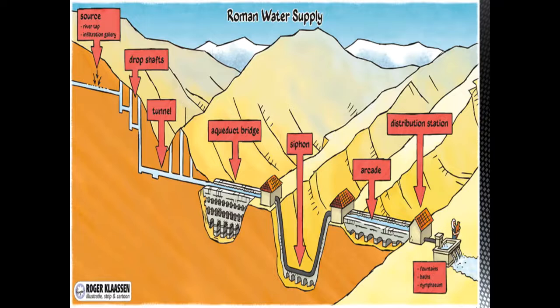Sometimes smooth chutes or stepped cascades were used to dampen the wave energy when the hill is too steep. The water comes down really fast. You don't want this water to break your aqueduct. So what you do, you make a cascade, you make it come down level by level so you can lessen the impact when it comes down the aqueduct.